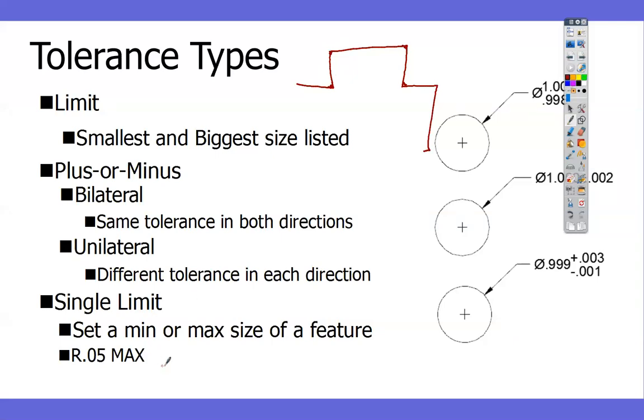And so that's kind of this. I would just throw that in everywhere, even if they didn't call that out, because it's not going to affect anything. Because sheet metal stuff, it's in the flange right here. No one's going to care about that. And actually, the sheet metal would go down. We'd do the bend relief right there. So I'd do that corner, that corner, that corner, and that curve. That one would be straight now. But I do all those corners, so it wouldn't stop and burn out as it did that little notch. Any question on this? All right.